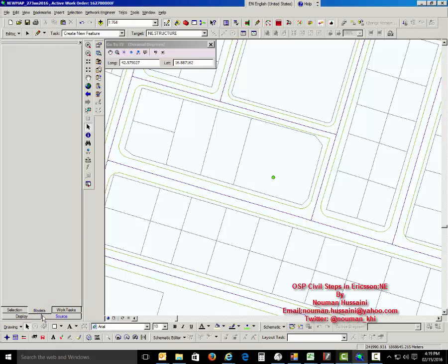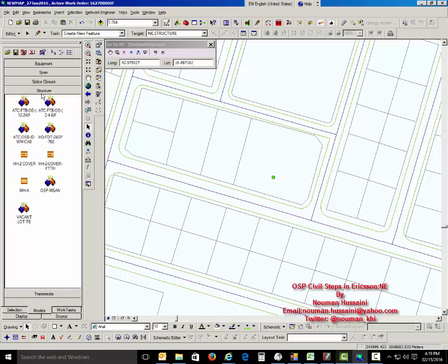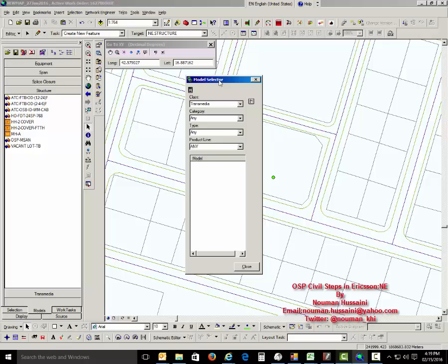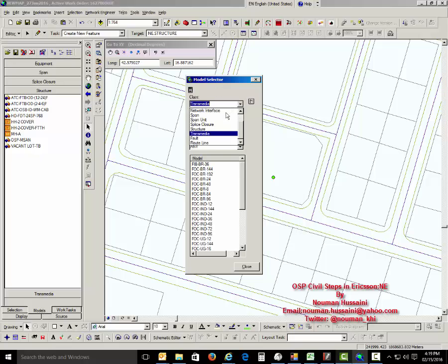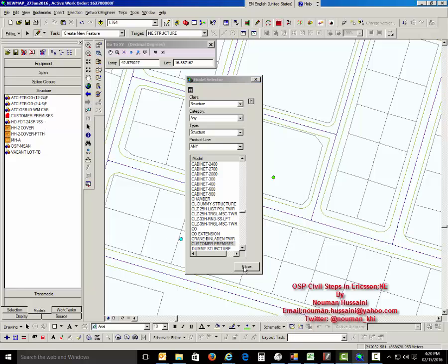We will use the tool button, go to XY, and we will type the coordinates and then zoom to the location. We can mark this location also with a green point. Now we will go in the tabs which is located in the table of contents, and we will select the models tab, and from the models tab we will click on the structure model, and in the types of models we will select the customer premises. We will double click, so it will appear in our model palette.